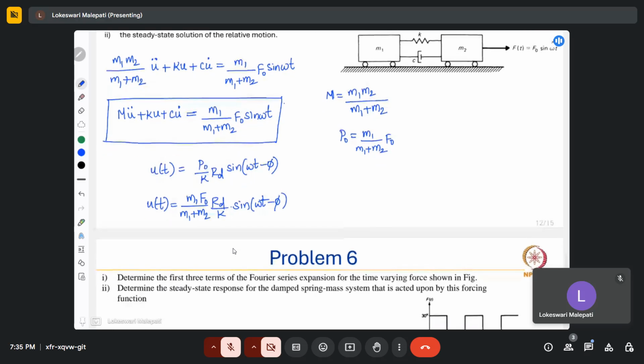In this we know the equation for phi. Phi is equal to tan inverse d by c. D is 2 zeta omega by omega n, and this term has no square here, and c is 1 minus omega by omega n the whole squared.